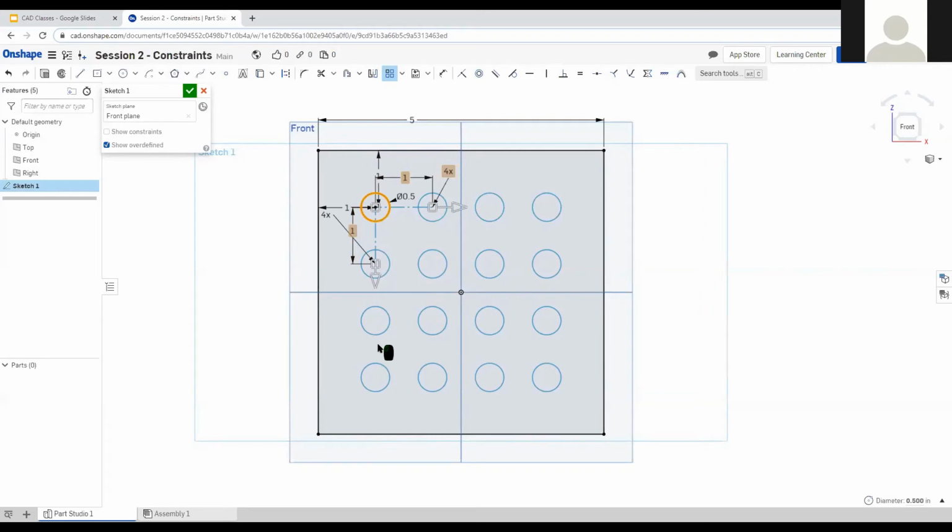Oh yeah, that's a good tip. So in chat, Bernard said, if you don't want a feature, primarily for the 3D features, like you're trying to extrude something but you changed your mind, instead of pressing that check up there, you can press that X. It will get rid of whatever feature you were trying to make. That's how I canceled the extrusion from earlier.